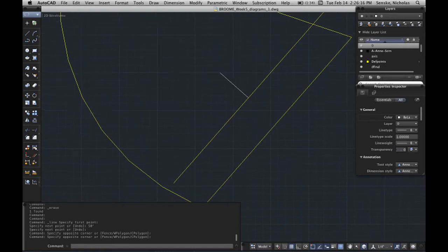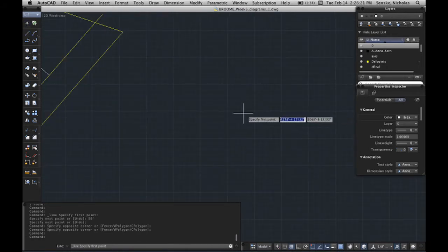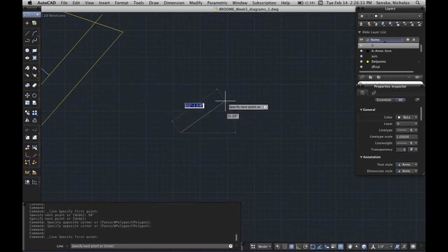That's a technique. Okay. To take a step back, if you want to draw a line in space in AutoCAD, right? There's lots of different things. So you can pick a point. So when I start the line tool, it says specify a point. So I can click to pick a point. Now at this point, if I have dynamic input turned on, there's a type-in that's the length of the line, and then I basically pick a direction.